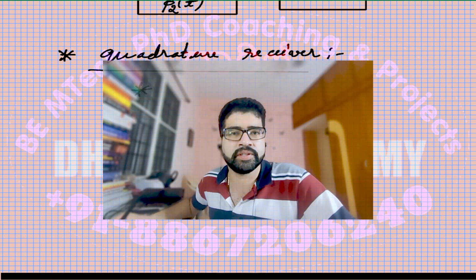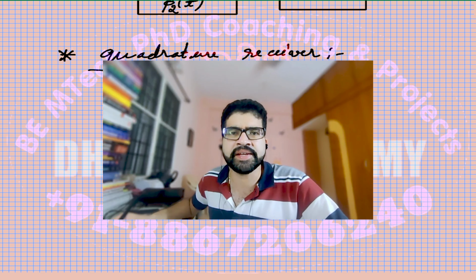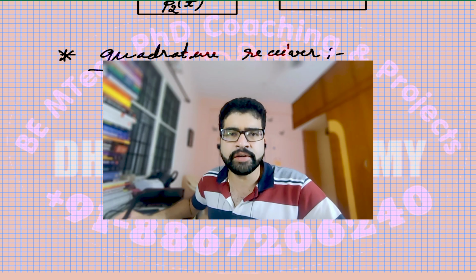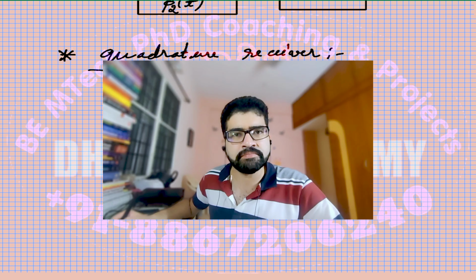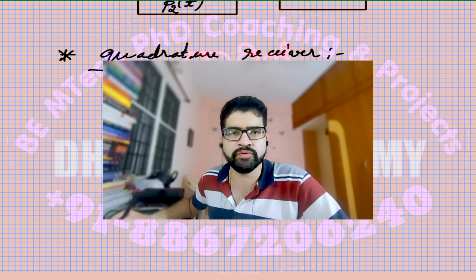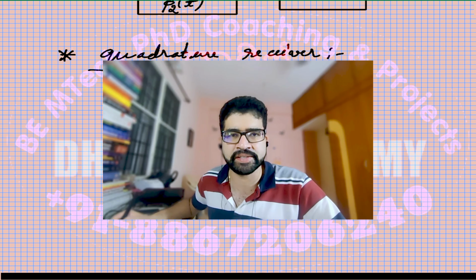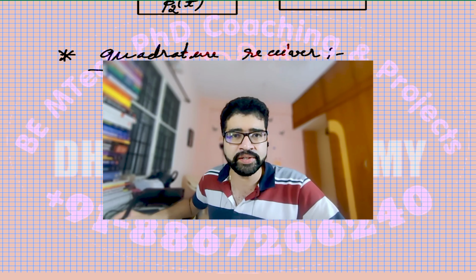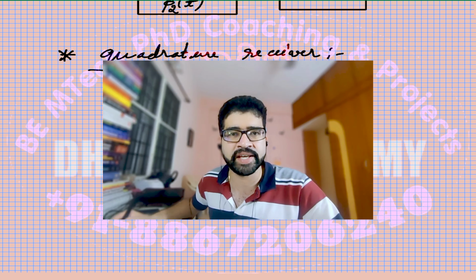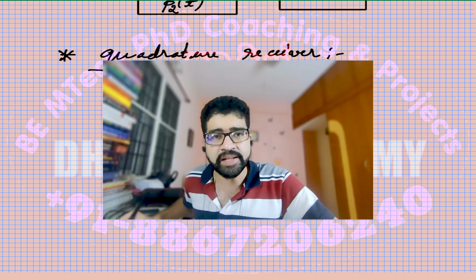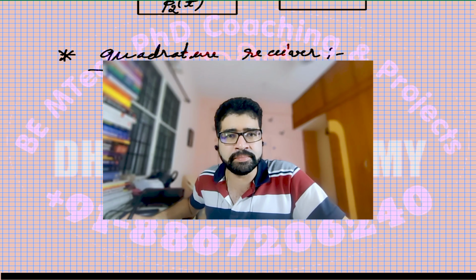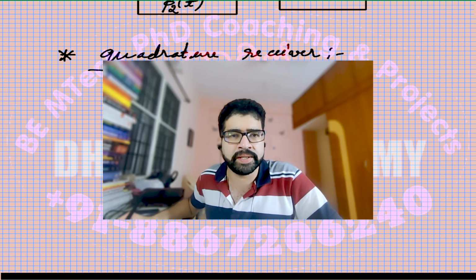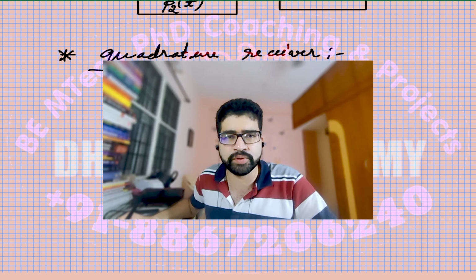We have many applications. Anything other than ASK is considered to be the simplest one. But when we go for slightly complicated techniques, which use multiple symbols, like QPSK, where quadrature indicates more than two symbols, like 4, 16, 8, etc., the constellation diagram also becomes very complicated, right? Under such cases, when you have multiple symbols, we expect many phi values to be present so that each symbol can be represented over a phi value.